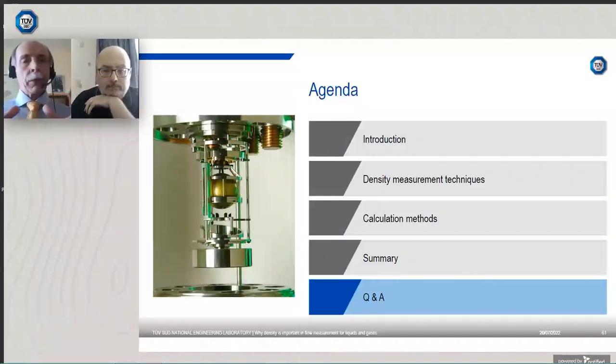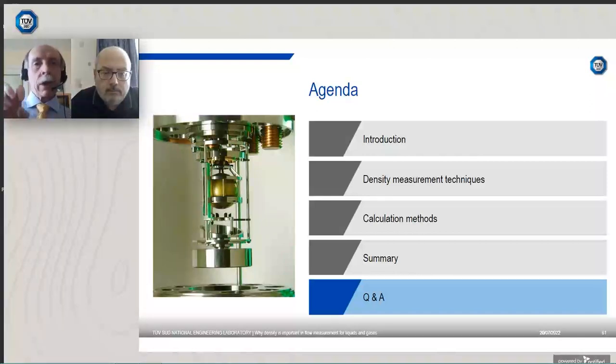For a natural gas mixture, the critical properties for each of the components are broadly similar. So you end up with reduced parameters that are numerically roughly similar. For hydrogen, the critical properties are so much different that the reduced parameters have very different numerical values. So that's the underlying chemical physics of it. What that does is it causes the mathematical solvers that you use to struggle, and systems with hydrogen, even using the best equations like the GERG equation, for example, sometimes for certain compositions just won't solve. Mathematical limitation.